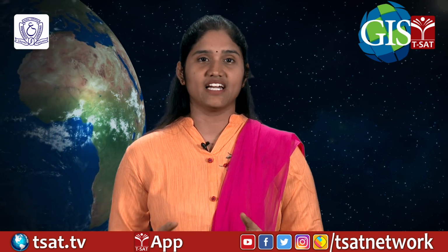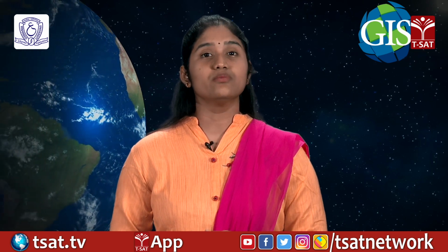Working with coordinate systems in GIS. The basic GIS tasks with coordinate systems involve defining a coordinate system, projecting geographic coordinates to projected coordinates, and reprojecting projected coordinates from one system to another system.